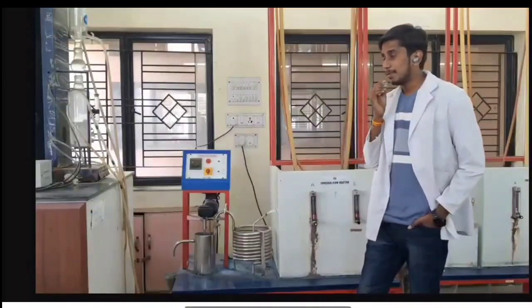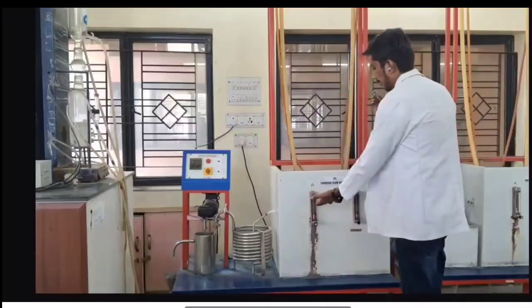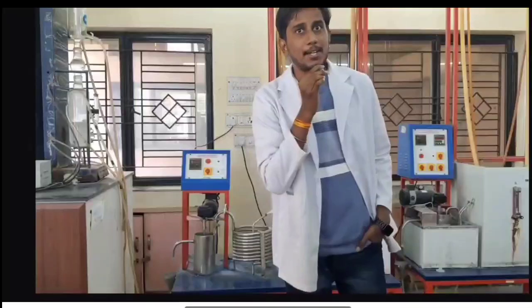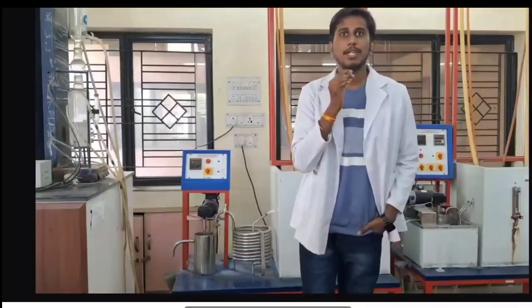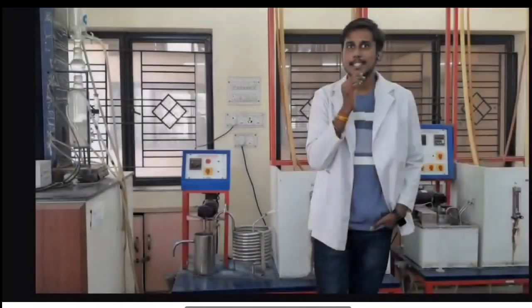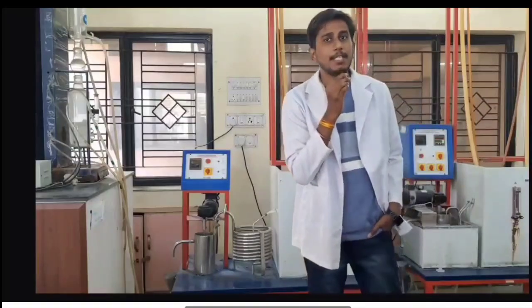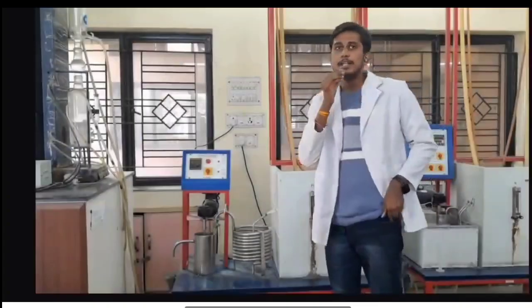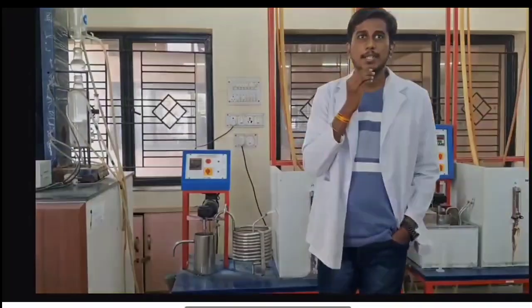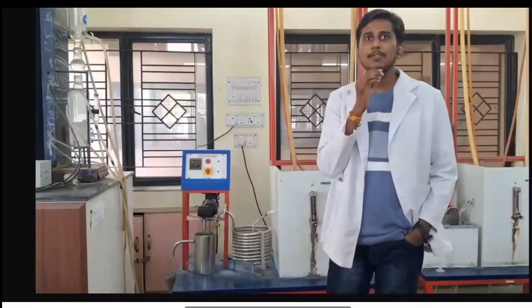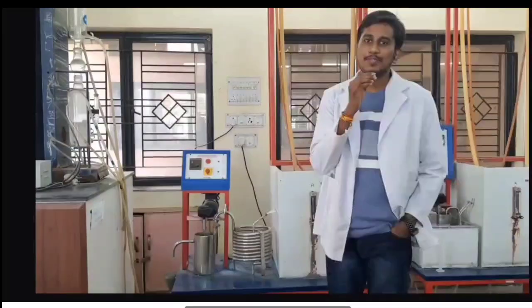Now here is step 2, that is adjusting the flow rates of both the reactors. So we will set up the flow rates of our NaOH and ethyl acetate solutions. Flow rate control is essential because it determines the time the reactant stays in the reactor, affecting the conversion also. Understanding the flow rate and its importance: we control the contact time in the reactor, which influences how far the reaction progresses in each of the reactors.